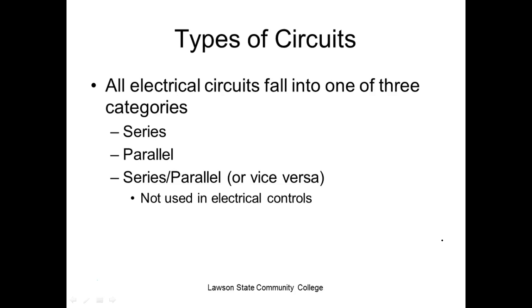Parallel is pretty easy. What we found out is a lot of people, once they learn series, they try to apply it to everything. What's nice is that in this class, guys, we have no series parallel circuit. In motor controls, there are no series parallel circuits. In fact, we have no multi-load series circuit. In motor controls and PLC, we either have one load series circuit, or we have multiple load parallel circuits.